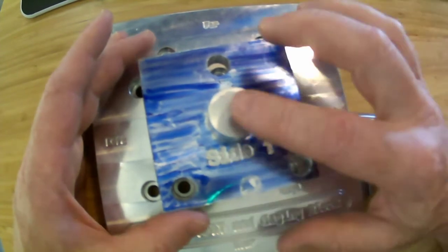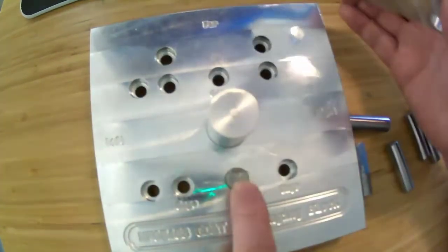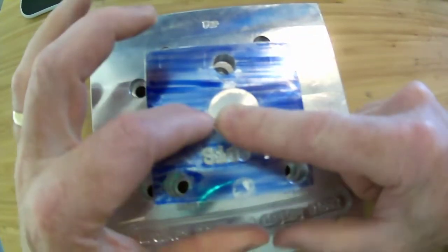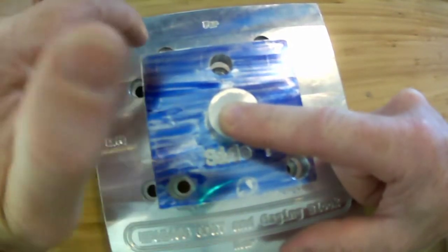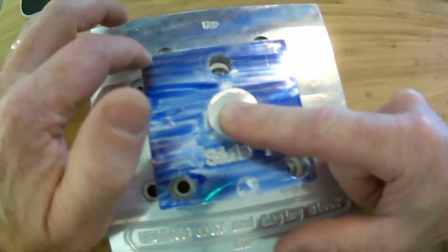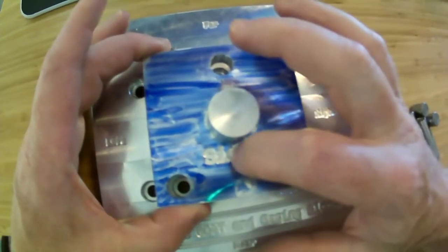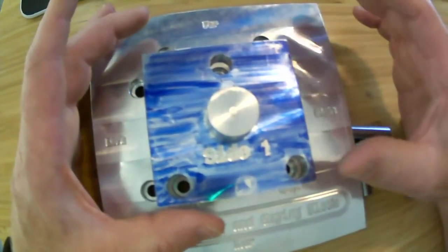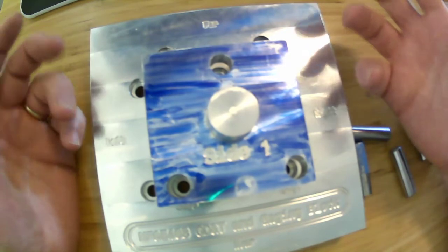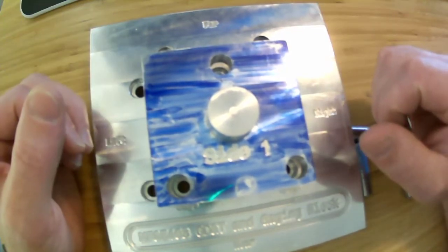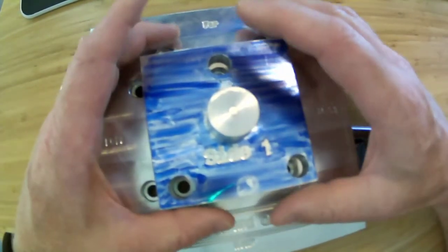Okay, that might be good, but notice that it's not very stable because I'm only supporting it on the bottom right here. And then I'm depending on this to provide moment support against the rotations around X or Y. So if I were machining over here and pressing down really hard, you can see that it lifts off that pretty easily. So it would take a monster clamp to hold it in place if I were going to do this. That's a place where determinism may ask for one solution, but in fact stability may ask for another. So what would I do in that case? There are several things I could do.